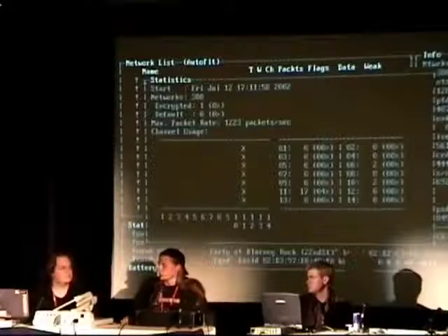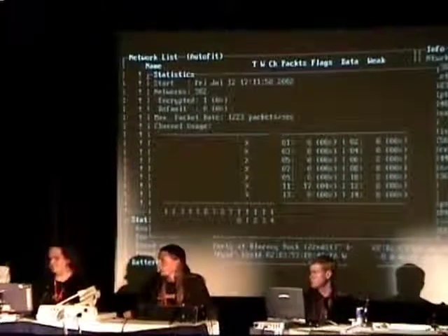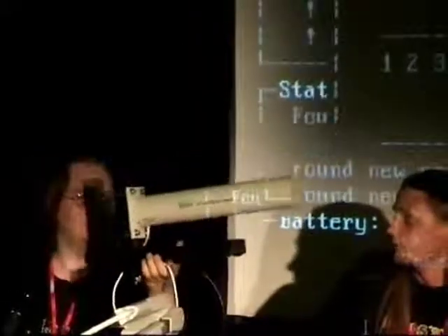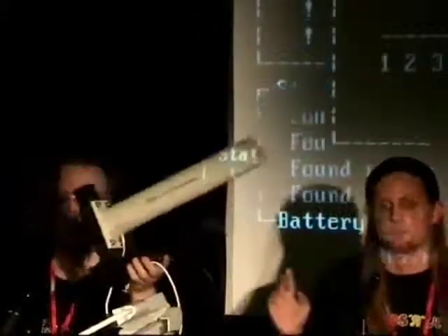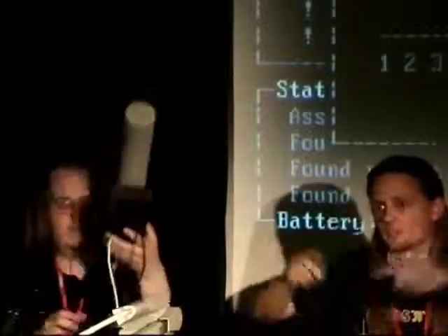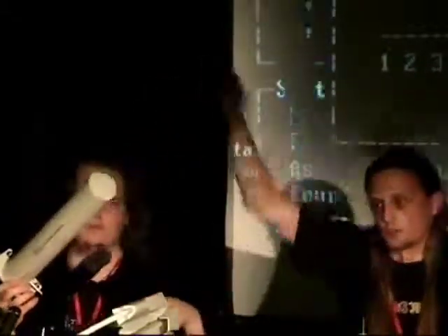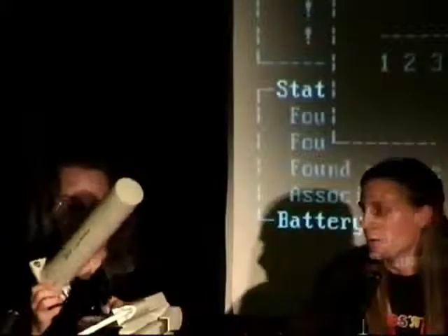Let's start with antennas, the different antennas we have. One of the best antennas we have is a Yagi. This is 14.5, I believe, 14.5 dB. Very directional. The distribution pattern, you would think, is sort of like a cone-ish or straight-ish. It actually has a little bubble in the front and then sort of goes out in a thin cone.